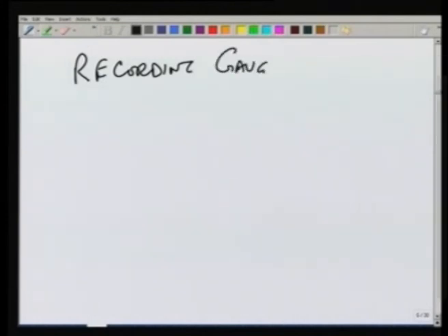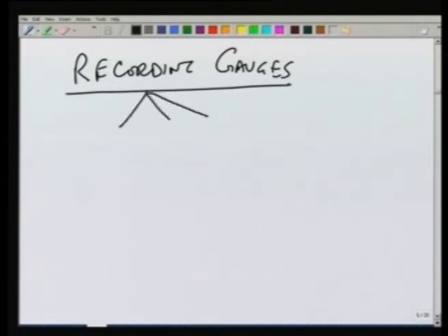The disadvantage is that it will not be able to capture the variation with time. So, we know that in a day there is, let us say, 5 centimeters of rain, but we do not know when it actually occurred or what was the intensity at different times. So, for that, a recording gauge is used, and these generally three common types of these gauges are tipping bucket,